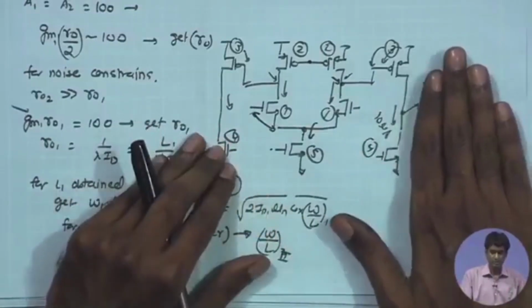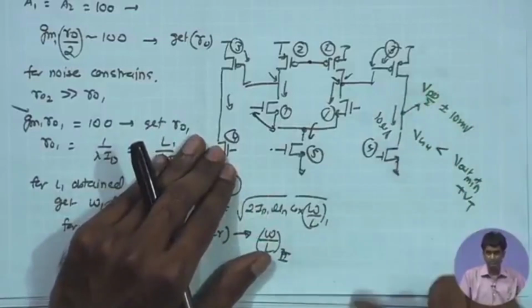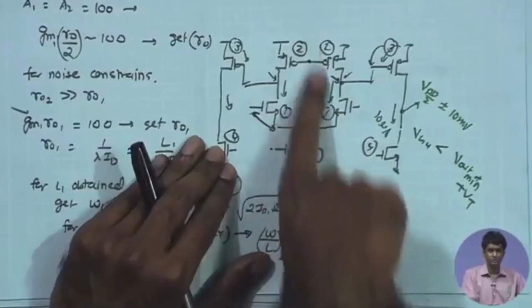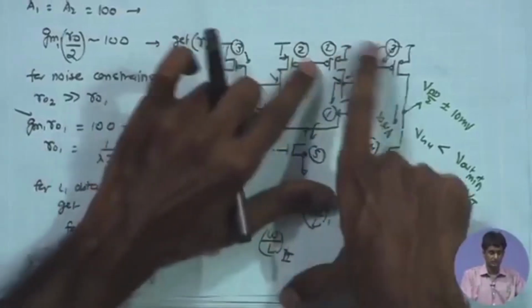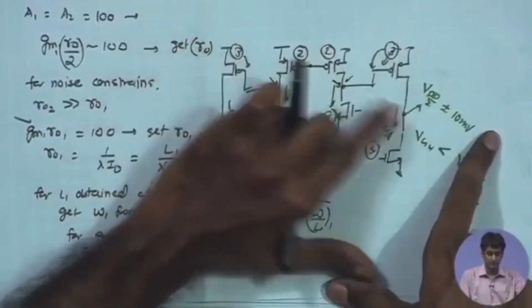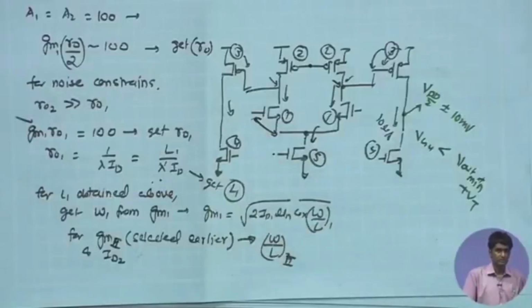We may not really worry a lot about the common mode feedback amplifier, because just like the current source contributes in a common mode fashion, likewise the common mode amplifier noise over here will also contribute in a similar fashion.